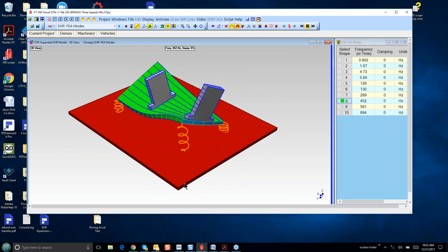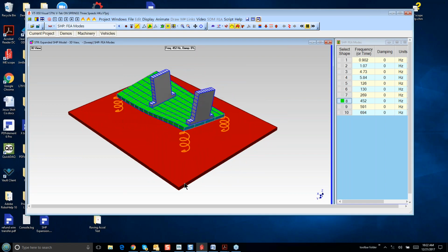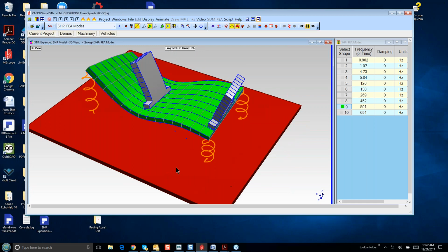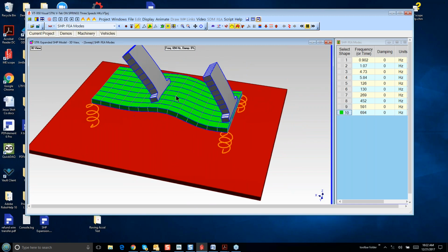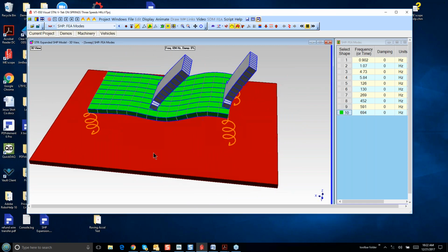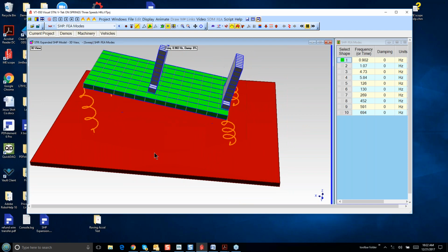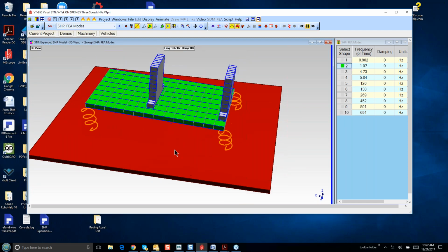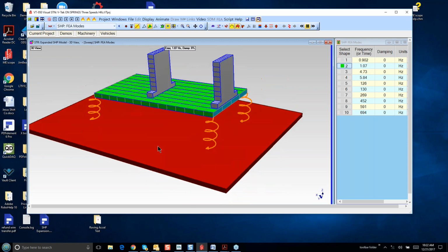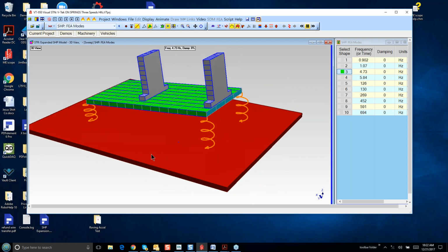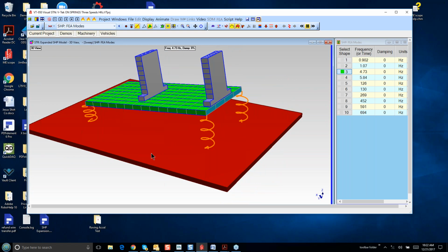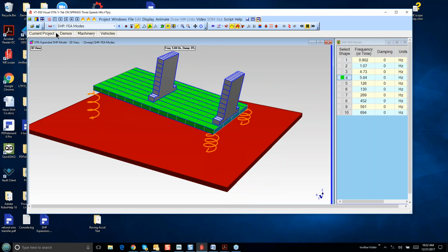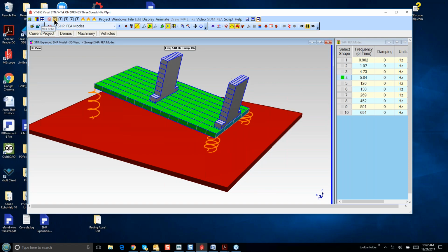Actually, the way we built this model was we put very stiff springs between each of the bearing blocks and the base plate, because the points don't line up. So you've got to attach them with stiff springs. SDM basically gives you the same answer as the FEA solver in ME'scope. So this is the FEA mode shapes. Now let's go press the next hotkey here.